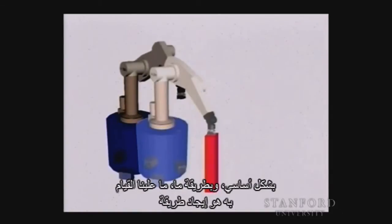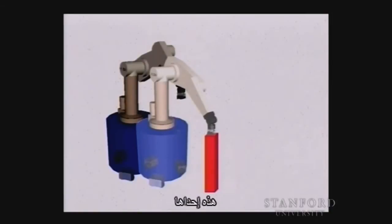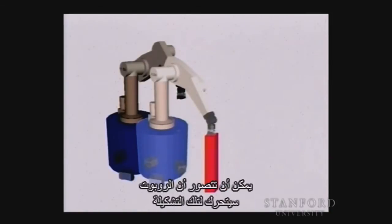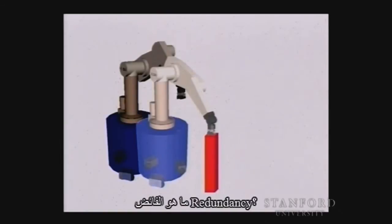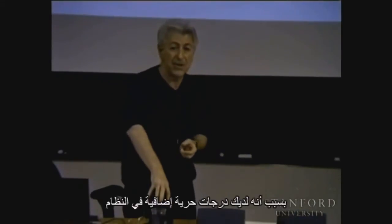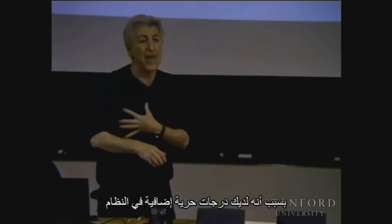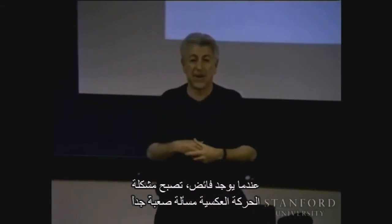Well, we said essentially what we need to do is somehow find a way of discovering a configuration through which the robot reaches that final goal position. And this is one of them. You can imagine the robot is going to move to that configuration. But the problem with this is redundancy. What is redundancy? Redundancy is the fact that you can reach that position with many different configurations because you have more degrees of freedom in the system. And when you have redundancy, this problem of inverse kinematics becomes a really difficult problem.